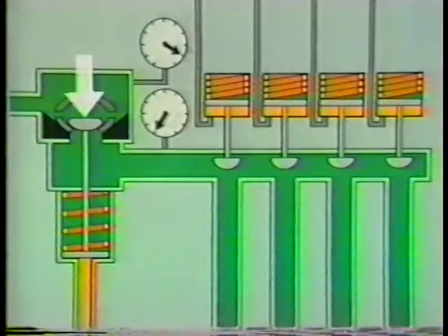We've also included 2 steam pressure gauges. This gauge indicates the pressure from the boiler to the main stop valve. And this gauge indicates the pressure from the main stop valve to the control valves. During startup, all of the control valves are usually wide open, and steam flow is controlled by the main stop valve's internal bypass valve.